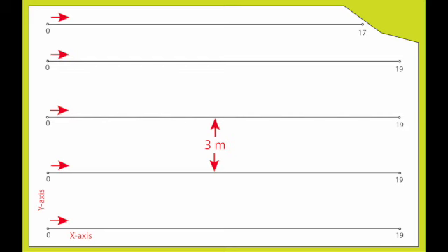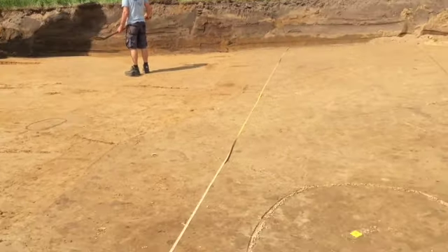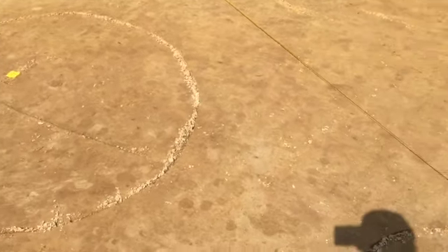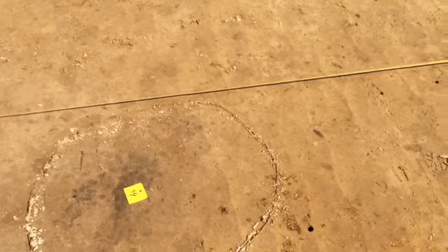The grid is laid out in the trenches with measuring tapes at 3-meter intervals as much as possible. The 0 point is preferably in the southwest of the system. The X-axis runs from west to east and the Y-axis from south to north. The 0 ends of all the tape lines start at the same site. This interval of 3 meters between the tape measures guarantees the quality of the measurements while still maintaining overview of the features. The main grid points are indicated with plastic tubes.